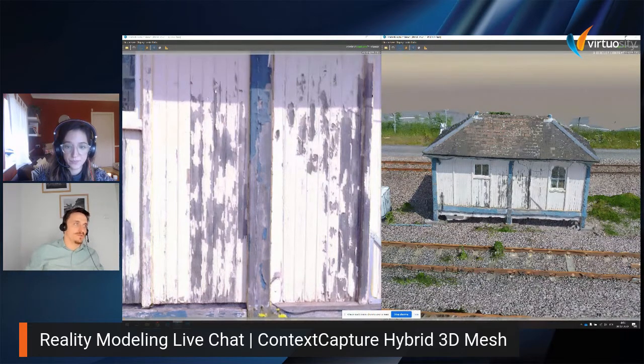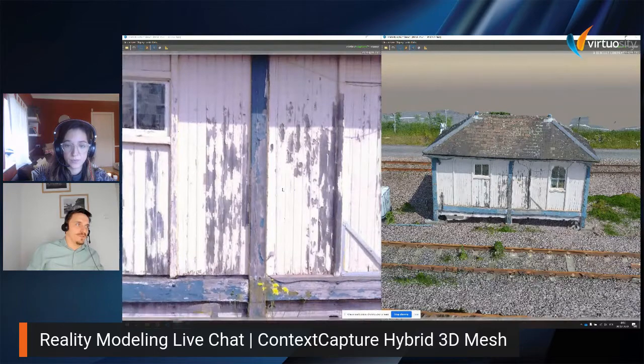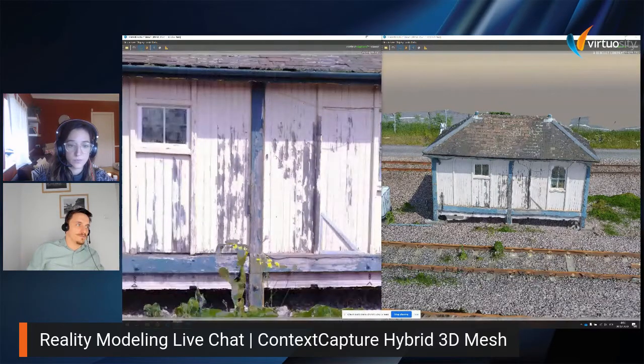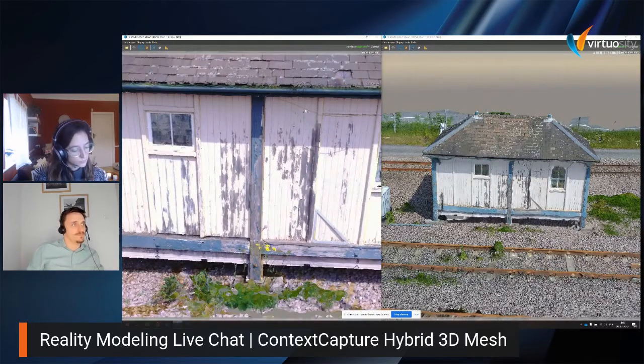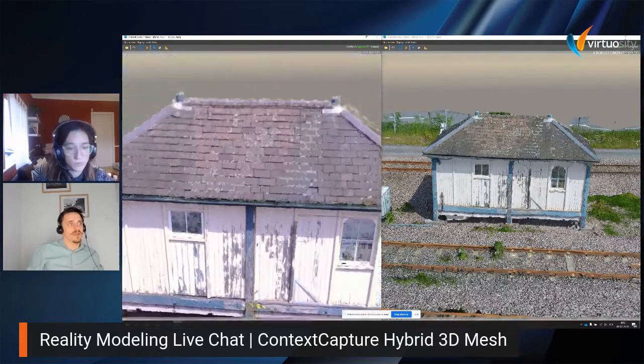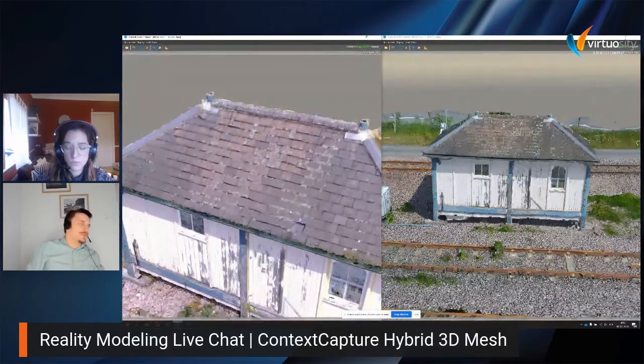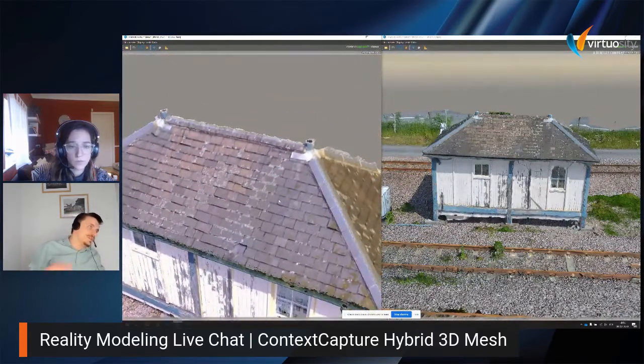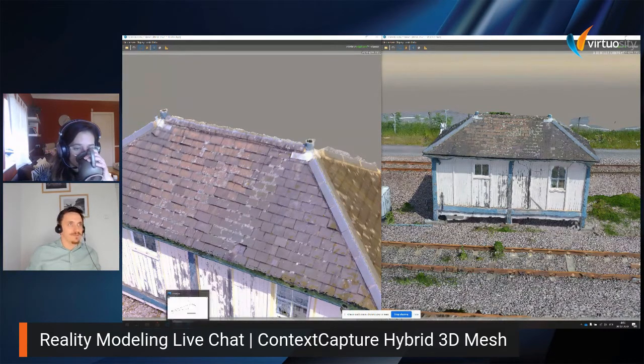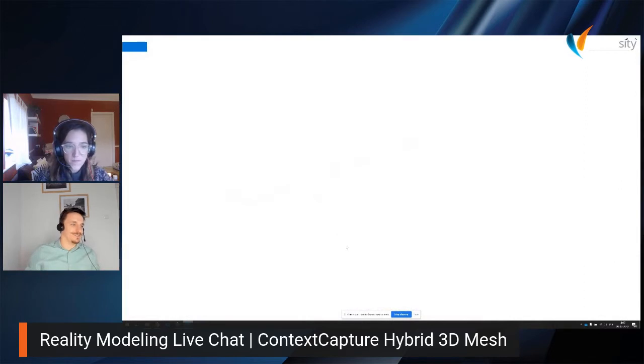Also, what is important, there is one bigger advantage in the case of scanning buildings mostly: the roof. We can scan a roof. That is not a problem, because we can use a range of the scanner which could be even a few hundred meters, and even more if we are talking about impulse laser scanning.